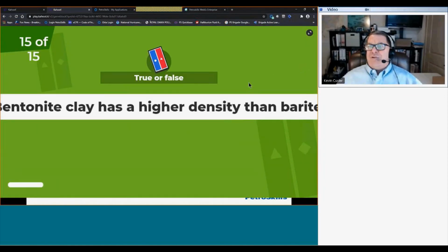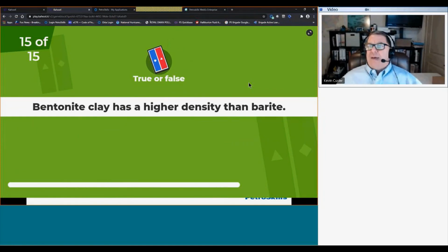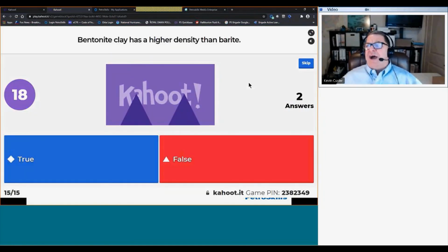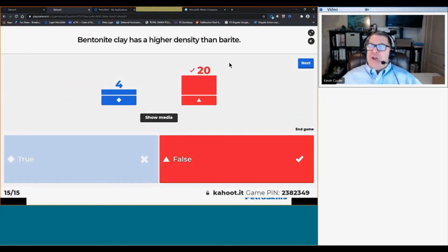Here's our final question. Bentonite clay has a higher density than barite. Wow, it's only 22 answers already. We still have 10 seconds to go. Bentonite clay. Well, we know bentonite clay has specific gravity of 2.6. Barite is 4.2, so that answer is false.